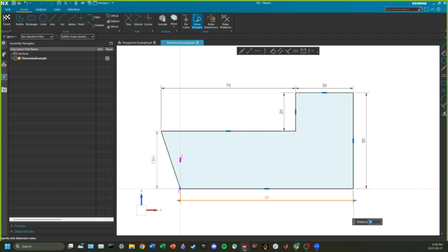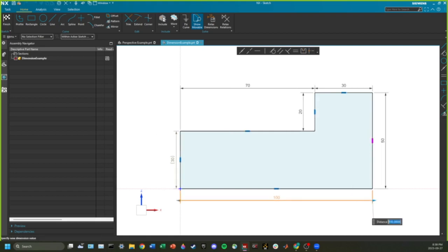This happens even if, under SolidWorks, you can say, I want a line to be horizontal, I want it to be perpendicular, I want things to be collinear. So you've got two lines like this, parallel like that, right? Perpendicular, it's all up here. Tangent button, if they should be equal length, yada yada. Those will break because those are driven. The driving dimensions will break the driven dimensions if you edit them.